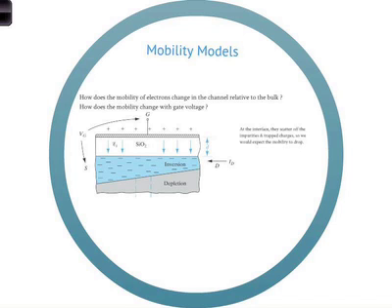So the next question was, how does the mobility change with gate voltage? I kind of answered that. If you plot mobility as a function of gate voltage, you would expect it to drop, right? Because of the extra scattering. So the higher gate voltage pulls the electrons closer to the interface and induces more scattering and essentially decreases the mobility. So you would expect at some point that the current should come down, which is what we saw in the transconductance plot before. Okay.